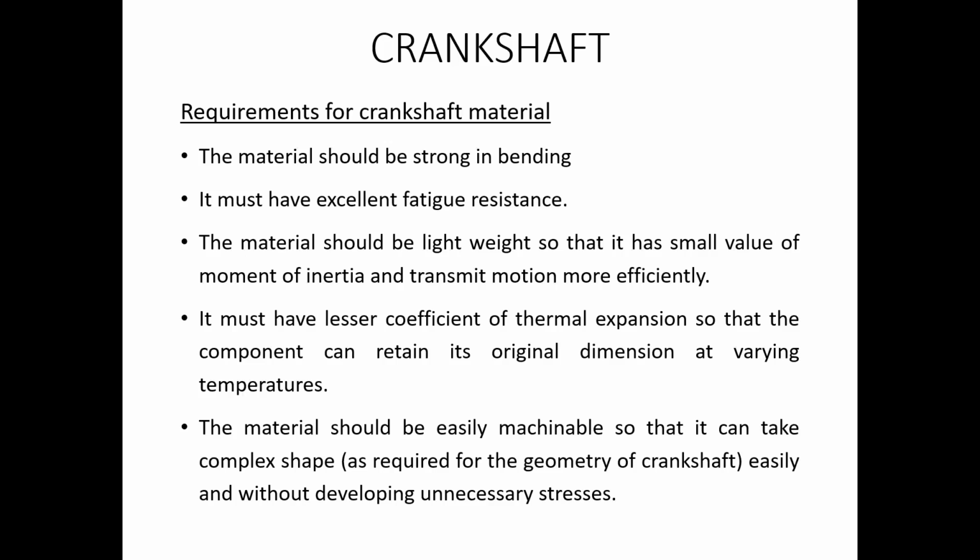Fatigue failure means the failure of the material due to cyclic loading, and the material fails prematurely, much before than is expected. So that is known as fatigue failure. So the crankshaft can undergo fatigue failure due to cyclic loading. Therefore, the material used for the crankshaft should have excellent fatigue resistance,